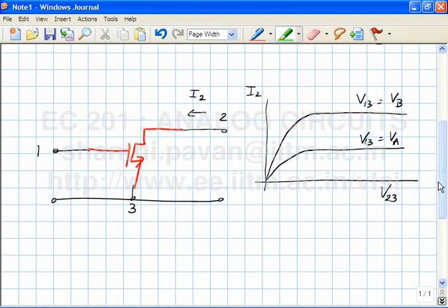And what did we say for VA and VB? The MOSFET will not conduct for any old VA and VB. It will only conduct if VA and VB are greater than some minimum quantity called the threshold, and the threshold happens to be a positive quantity, in most devices. There is no earthly reason why VT can't be negative. If VT is positive, it's called an enhancement mode MOS transistor.